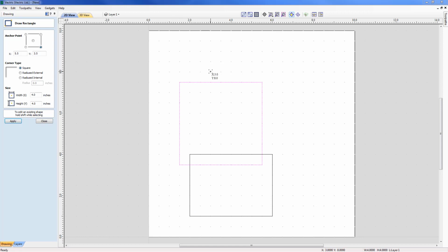Now, just like with ellipses, we can use the screen to specify either the X or Y and then use typed entry for the remaining value. So I'm going to start by entering my top left-hand position, and as you can see, I'm stretching the rectangle, and I know in this case I want a width of 2, but my height I want to specify as, say, 5.25. So I can type in 5.25y, and that will give me exactly the correct distance in Y for that parameter.